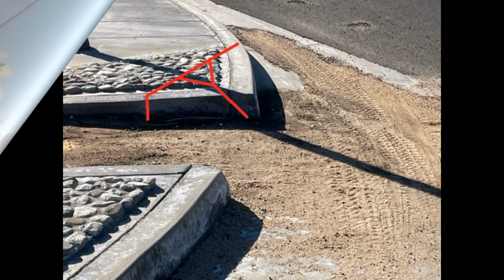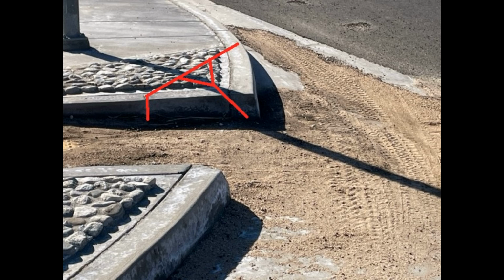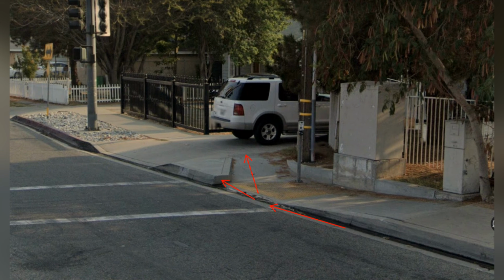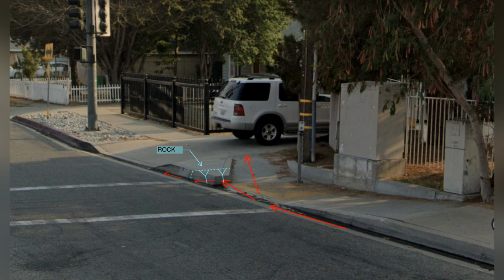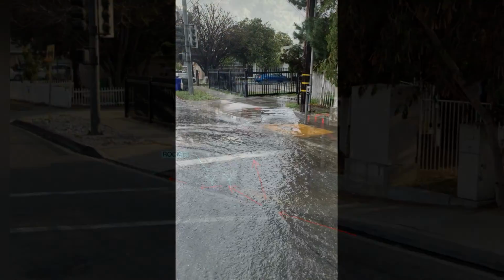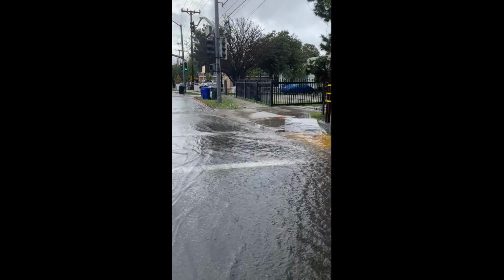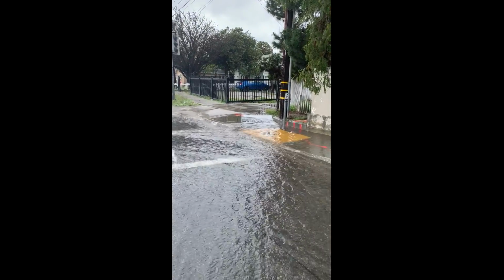I have also noticed when designing a curb-style ramp that the downhill side of a cross-gutter will always divert more water and silt onto the ramp. I believe a good alternative to this is to design the downhill side with a flare so it will divert most of the flows and silt back into the road. As you can see with this video, a lot of water is diverted back up the ramp and onto private property. To help this problem, adding a concrete wing with rock will help divert most of the flows back into the street.